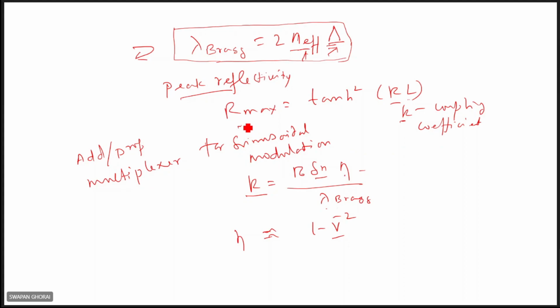Reflection coefficient, peak reflectivity when the Bragg condition is satisfied, and these are Bragg conditions. Which particular wavelength will be reflected depends upon this n effective and capital lambda, that is the grating period. This is a coupling coefficient, and there is a peak reflectivity expression.